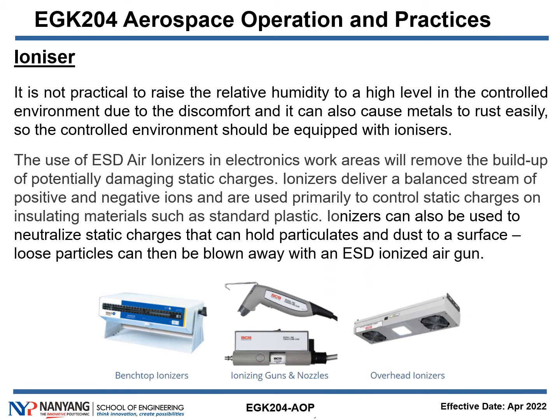Now, it is not practical to raise the humidity to a high level. Because if the humidity is high, there's less chance for electrostatic to take place. But to raise it so high is not comfortable for human beings. So what we do is use the air ionizer, the ESD air ionizer. These are the various types here. We have a benchtop, we have a gun, which is more directional on a certain area, or you have an overhead ionizer.